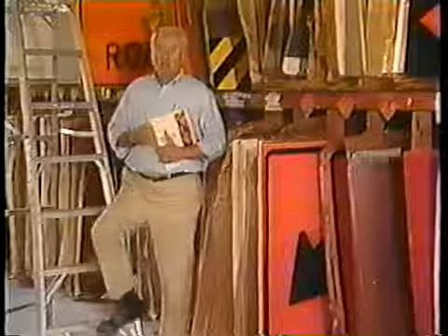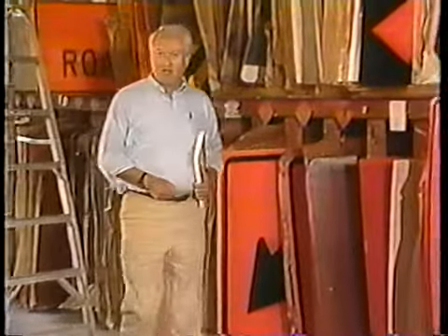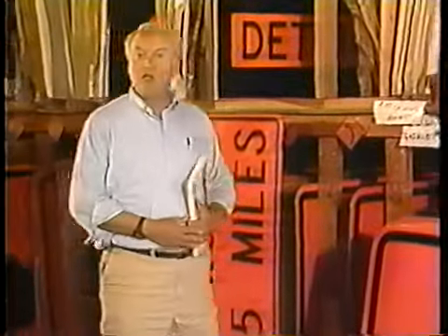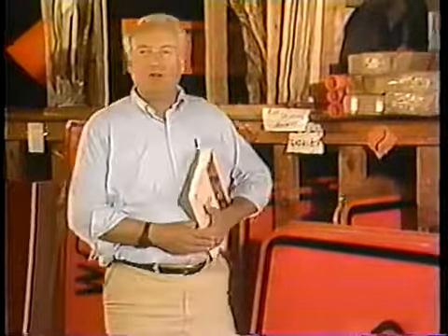Standard signs and messages, as shown in the Manual on Uniform Traffic Control Devices, should always be used. Drivers are familiar with those signs and they know how to react, but non-standard sign messages could be confusing. All signs should be made in a professional sign shop or purchased from a reputable business. Homemade signs are immediately suspect and do not command driver respect.